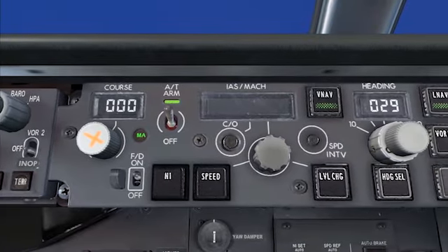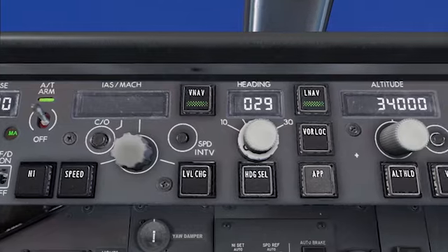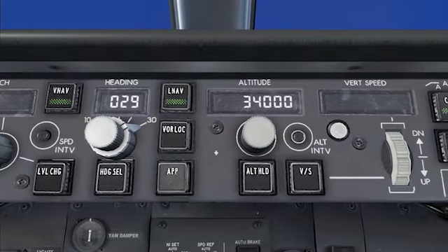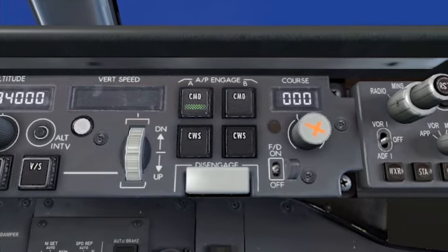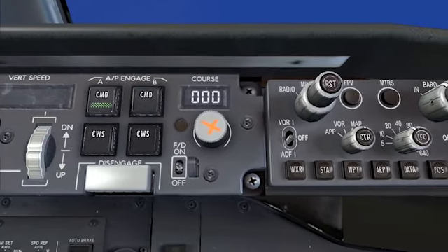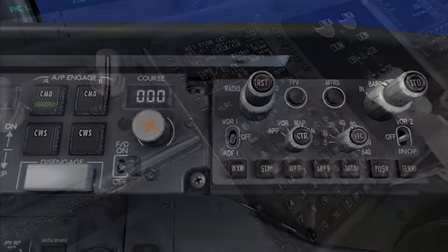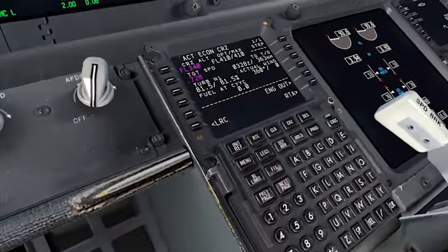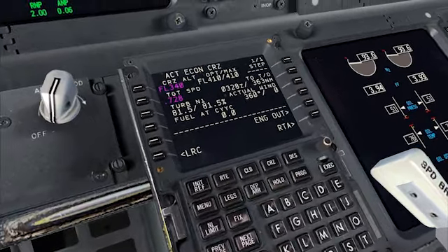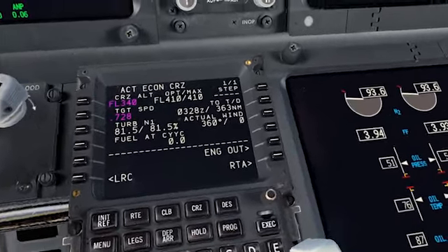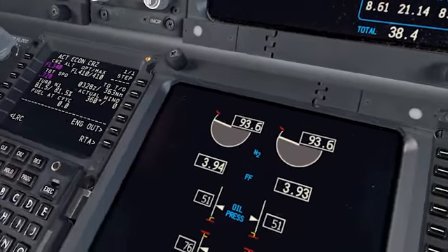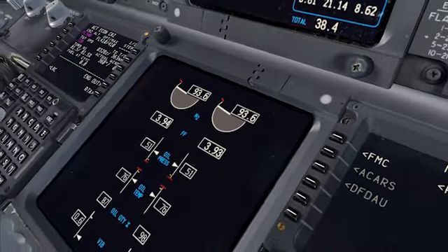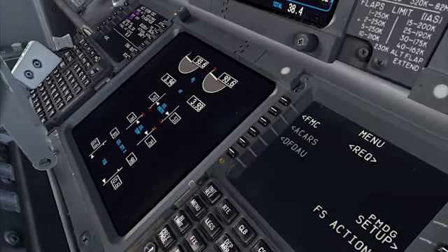If the FCCs are the brains of the operation, the AFDS is the management. This is where, as pilots, we choose which autoflight mode the aircraft operates in with the MCP, what automatic power settings the engines are commanded to with autothrottle, and also if we choose to use the complex FMC system to use various AFDS modes. Although technically the FMC is not part of the AFDS, we include it here because it's tightly integrated with not only the AFDS, but the FCCs themselves.